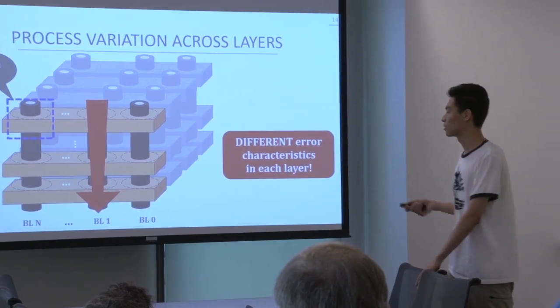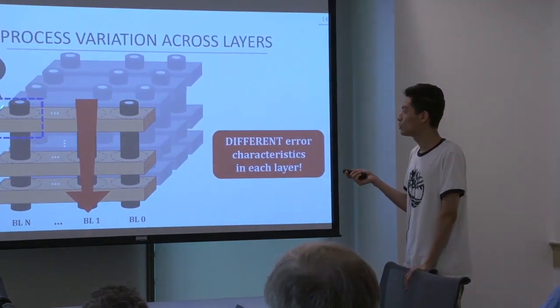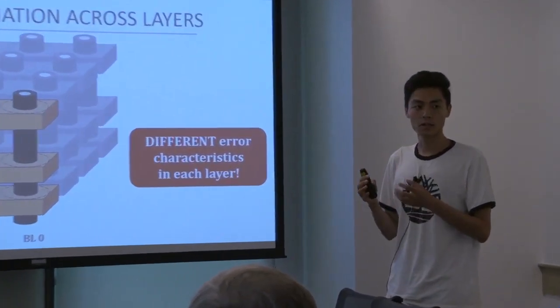Okay, yes, this is a good question. Basically, each flash cell holds a single unit of data. For the device that we characterize, which is a multi-level cell device, each flash cell holds 2 bits of data. Essentially, over the full column, you have 2 M bits stored.